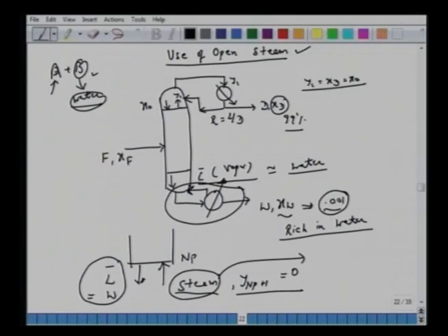In the McCabe-Thiele method, essentially what we do is write down the species balance or the material balance for the top column and for the bottom column. So you have two operating lines, they intersect, you have this q line, then you calculate the number of plates. You can also have the Ponchon-Savarit method, where you recall you have HV, the saturated vapor enthalpy, and saturated liquid enthalpy. There you locate the difference points at the top, XT, and the bottom, XW, and then you mark your tie lines and the operating lines.